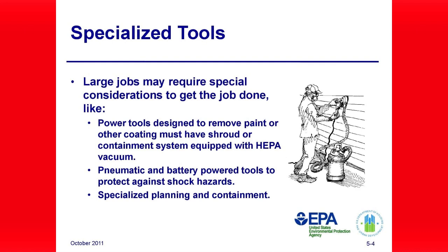Containment is even more important when using specialized tools. Proper containment and cleaning is crucial even when using a HEPA filtered specialized tool. These tools generate a lot of dust inside the localized negative pressure vacuum environment. If the vacuum fails, or if the vacuum seal created by the shroud is broken, large volume of dust can be released. Nonetheless, HEPA filter specialized tools can reduce dust levels when used properly and can aid work production by shortening the cleaning time and lowering costs.